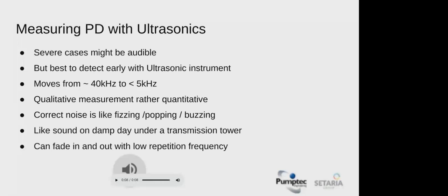So the correct noise is like a fizzing or popping or a buzzing noise. Sounds a bit like what you might hear if you stood under a transmission tower on a damp day. It can often fade in and out with a low repetition frequency as well. And it's important that it has that sort of crackle to it. Once heard, never forgotten, basically.